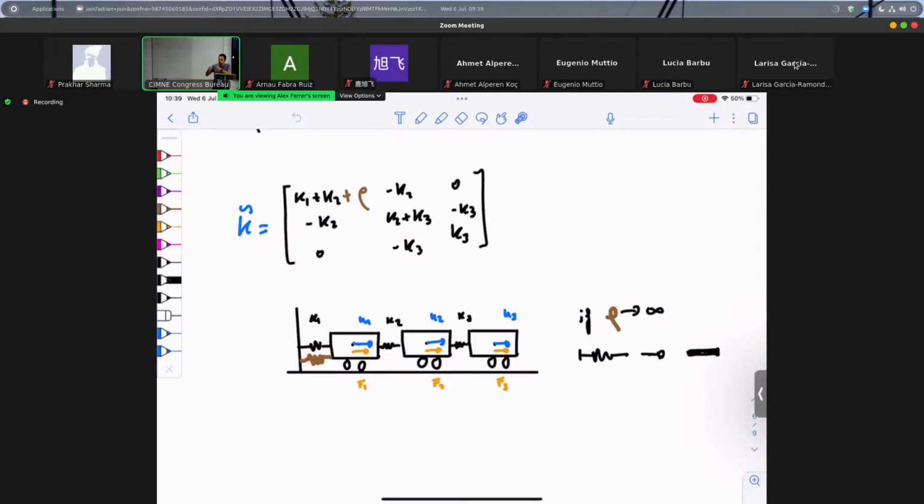So you have these 3 points, they want to move, you put forces, but you want the point on the left to be fixed. Okay, so to impose this condition of being fixed, instead of putting a penalty equal to infinity, a very rigid bar, people sometimes do these kinds of things. What you do is you put this spring. Then it's smoother. Of course, you can start with a very large value, and the larger this value, the more you are going to fix this constraint. And if it's very small, okay, you will get there, but it will take very much time. Okay, so there is this interpretation of the penalty method, the penalty parameter.